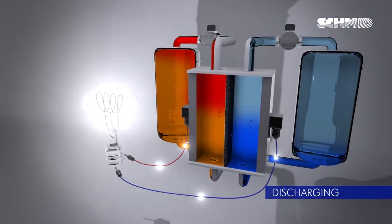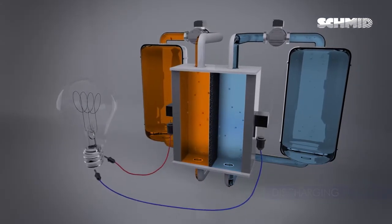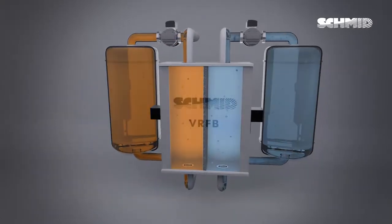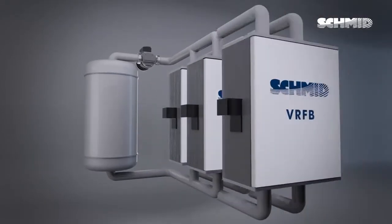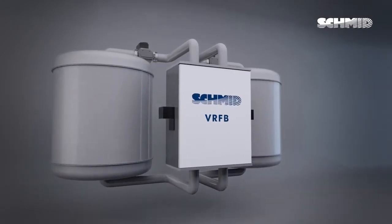The vanadium redox flow battery delivers electrical power until the electrolytes within the two tanks are completely discharged. The SCHMID vanadium redox flow battery can be independently scaled for appropriate power and energy. Power can be adjusted through cell size and number. Energy is defined by the tank volume to perfectly meet the customer's needs.